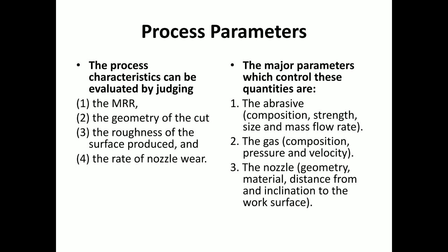Next is the rate of nozzle wear. How fast will the nozzle wear out? The nozzle has some life hours, so it will wear out. If the material is less hard, it will wear out fast. If it is a hard material, generally it has a life of 300 hours. After 300 hours you have to change the nozzle.